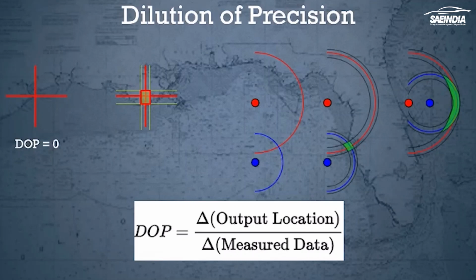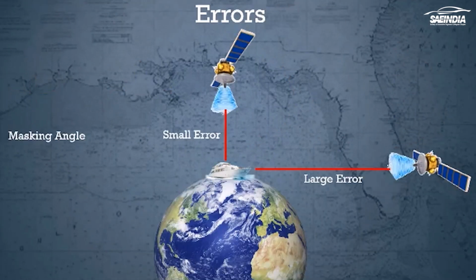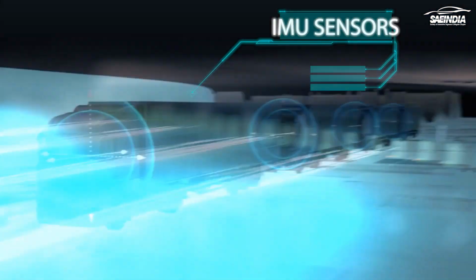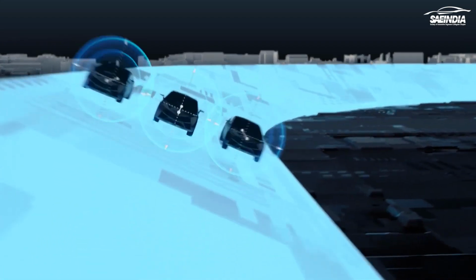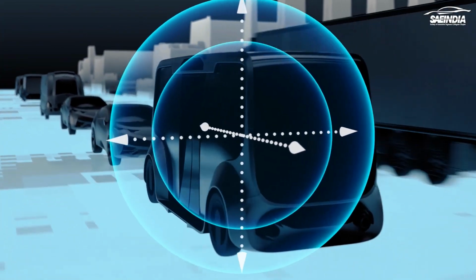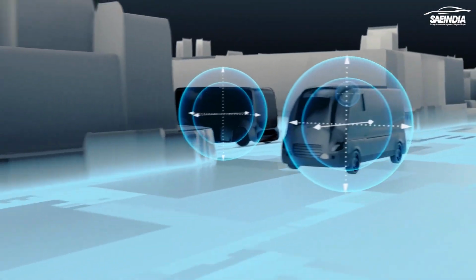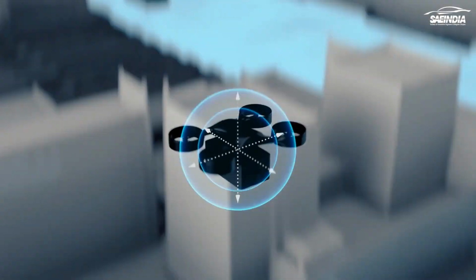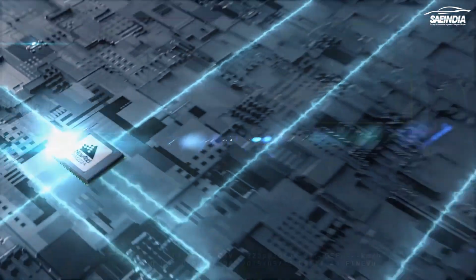The GNSS also takes help from inertial measurement unit sensors, that is IMU sensors, which are made up of 6 sensors in orthogonal axes, each axis having a gyroscope and an accelerometer. These sensors can sense the change in acceleration in all axes, so when GNSS is not available, they help track the position of the vehicle until the GNSS is available.